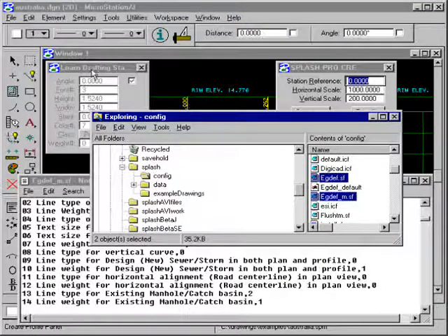The Learn Drafting Standards tool only affects text in profile panels. For items such as line weights and line styles, please refer to the Splash Config, Engineering Graphics Defaults file, and Engineering Graphics Defaults for Metrics file.